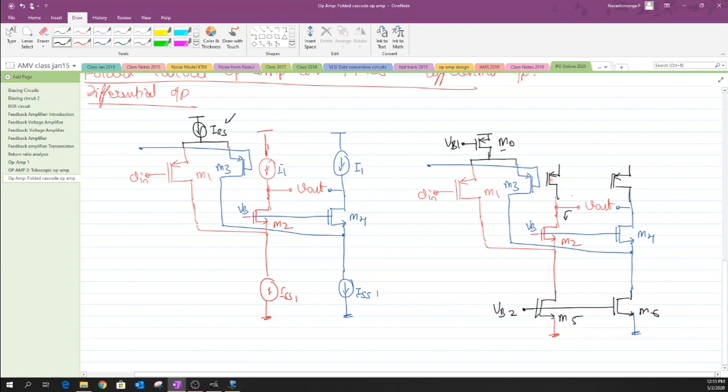a cascode structure. So let me just try to fix the bias voltage somewhere here, which has been connected to the gates. Okay, and let us label this as VB3. And similarly, we need one more structure at the top to be reflected, such that the impedance that we have should balance out the impedance that we have at the bottom of our Vout terminal.